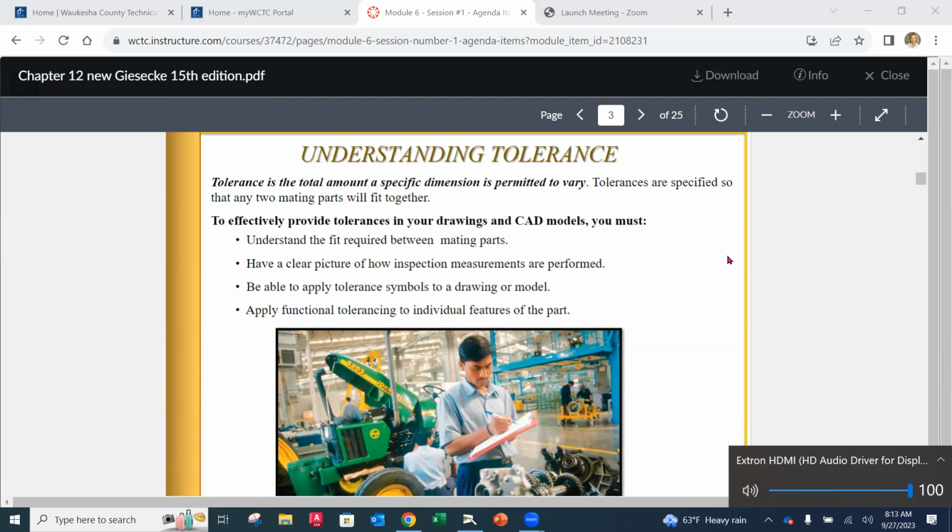Okay. So a tolerance is the amount that is allowed. We can't just willy-nilly set up 2 decimal places and say, here are the dimensions. You have to look to that title block and keep in mind what that plus and minus is, because now that's the target you've set for that dimension intentionally. You have to think about every dimension on there and its function, its purpose, how accurate it has to be, and how it's going to be manufactured.